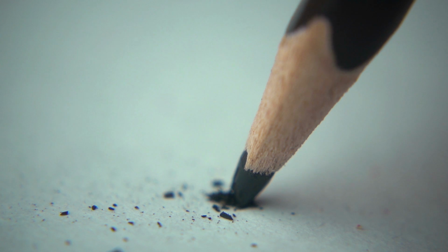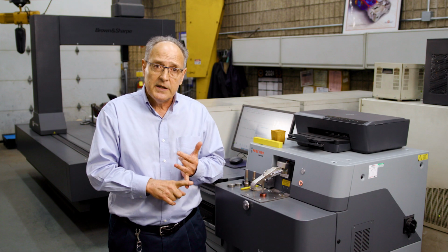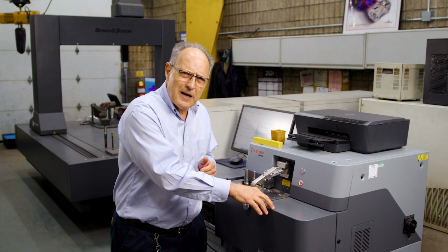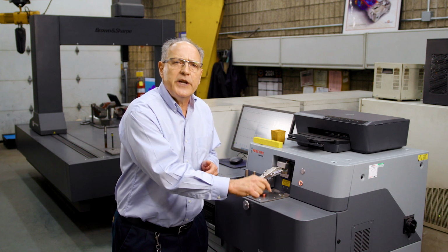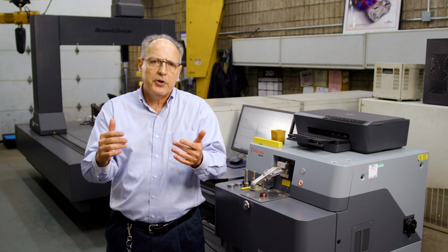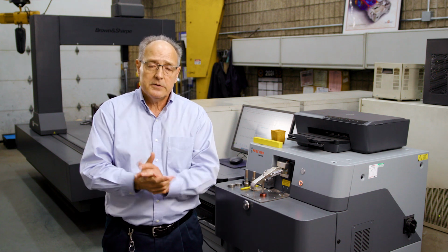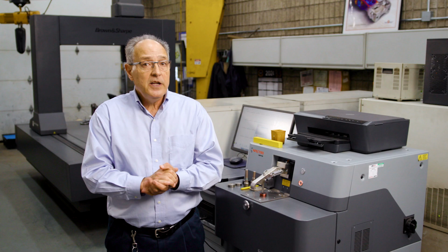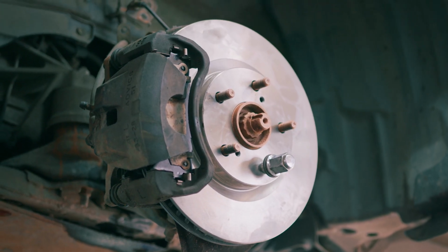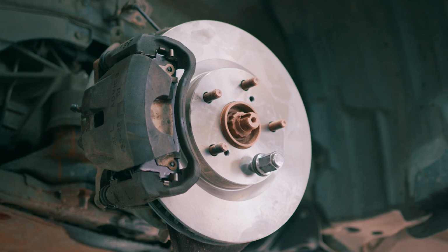So why would people buy gray iron if it's brittle? One reason is sound damping. That shape of graphite doesn't let the sound move too fast, so it doesn't ring. It's like a piece of wood. If you need an engine block or a brake rotor, you don't want noise, so gray iron is better. And graphite is a good heat conductor. Again, brake rotor, engine block, you don't want those to overheat, so gray iron is better for that. Ductile iron, you can make axles, you can make structural parts for tractors, so it's much stronger.